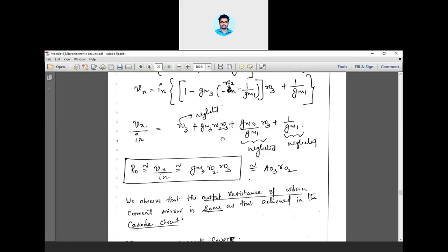certain circuits are not providing the suitable output resistance that a cascode amplifier wants. The cascode amplifier requires an output resistance of A0 into R0. So your mirror circuit should also have the same output resistance, and only then will the matching occur and maximum delivery of current will occur. That can be satisfied only in the case of Wilson's MOS mirror, not Wilson's current mirror.